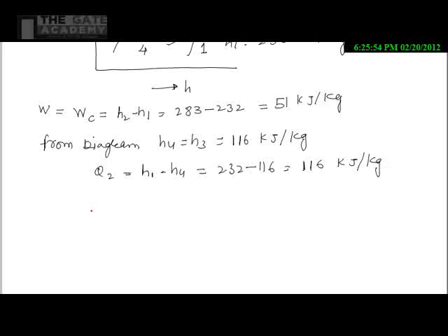So COP we can easily calculate. COP is nothing but Q2 by W. So 116 divided by W is 51. So 116 divided by 51, it will come 2.27. So the correct answer for this question is 2.27.